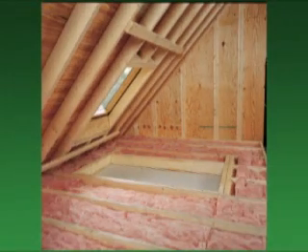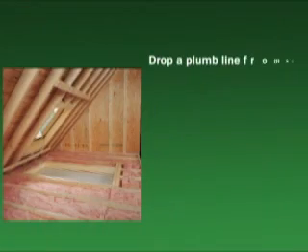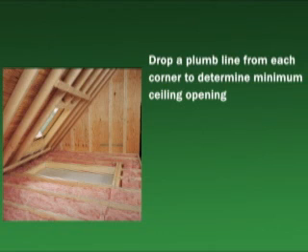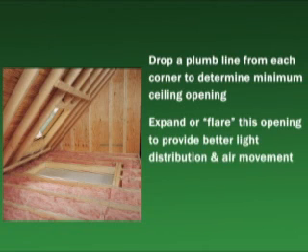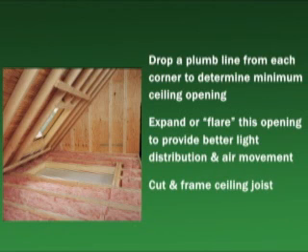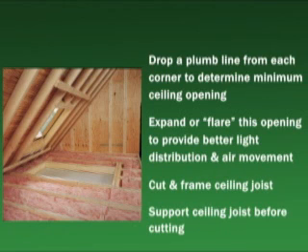Now we're ready to prepare and cut the ceiling opening. Drop a plumb line from each corner of the skylight to determine the minimum ceiling opening. Expand or flare this opening to provide better light distribution and air movement. Following the same procedures used to cut the rafters and frame the roof opening, cut and frame the ceiling joists. Be sure to support the ceiling joist before cutting.